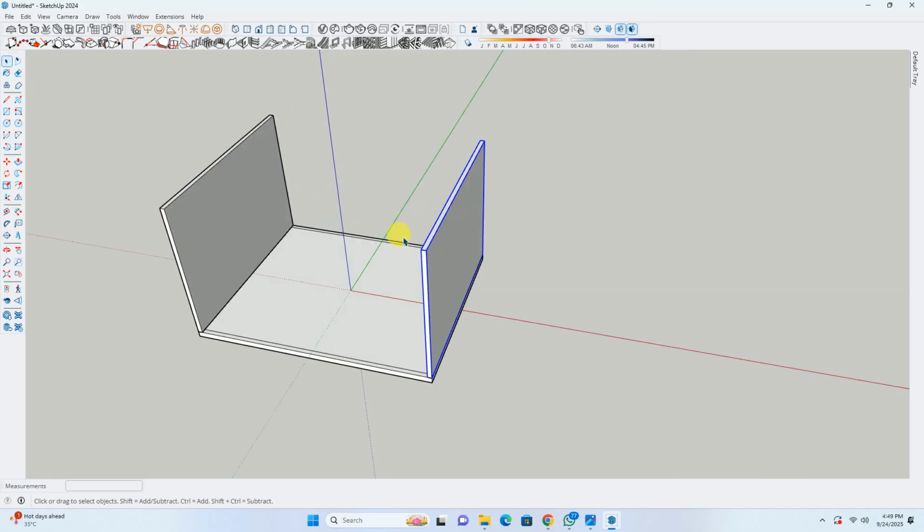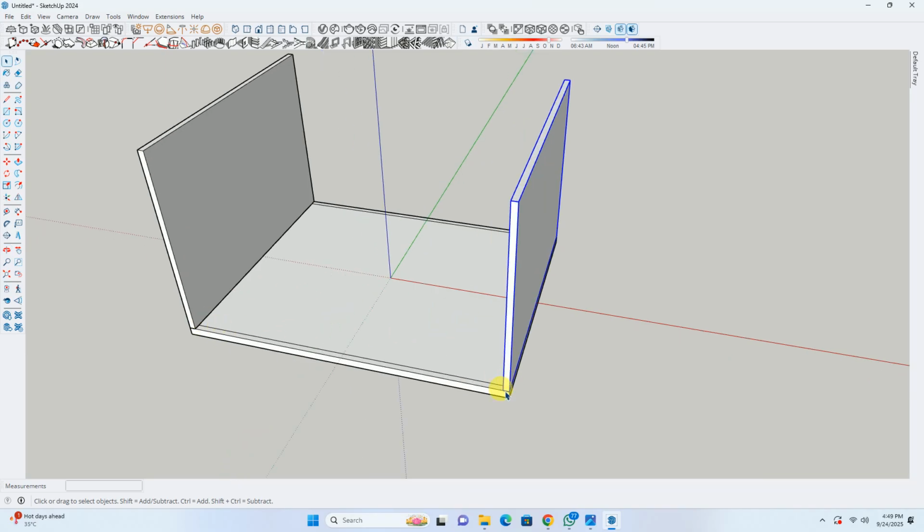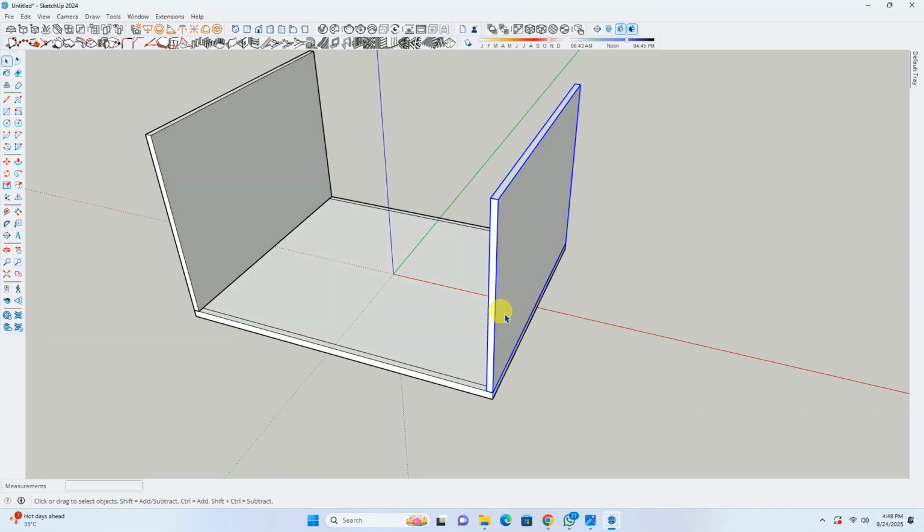Now we want another two walls over here. So what we can do is use the rectangle command again and create a rectangle over here, or we can rotate with copy. We can apply the rotate command because in the move command you can't apply rotation, but in the rotate command you can apply copy.